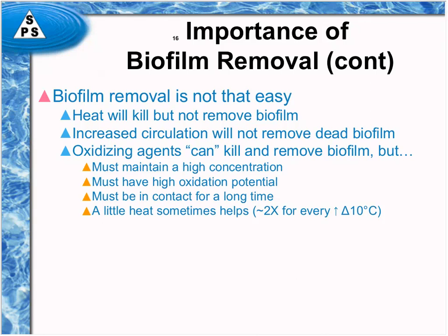Sometimes with some sanitants that are heat tolerant, like for instance hypochlorite, if you heat it up a little bit, it's very easily tolerant of hotter conditions. For every 10 degrees C that it's hotter than ambient temperature, you'll probably double the efficacy of the sanitant, up to a point, up until you start degrading it because of the heat. But typically that's a reasonable rule of thumb for those sanitants that are compatible with heat.